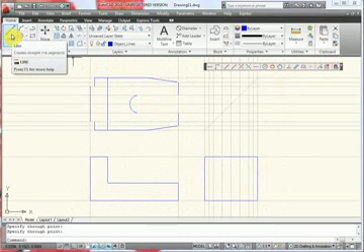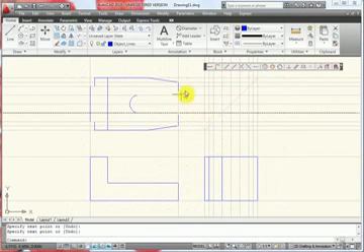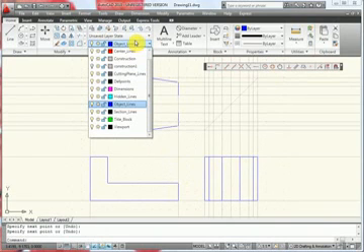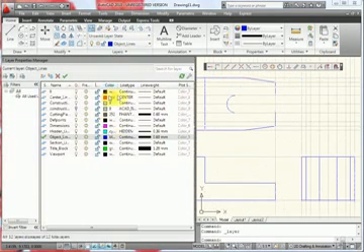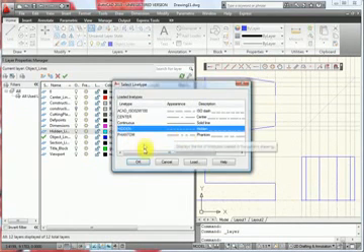I'm going to start filling in some of these solid lines. And remember, this is a view as if you're looking towards this object from the side. Next, I'm going to draw a few hidden lines and center lines, so you got to make sure you add those to your layers. That way you can use them, as well as make sure for the center line you add the center line for line type, and for your hidden line use the hidden line type.